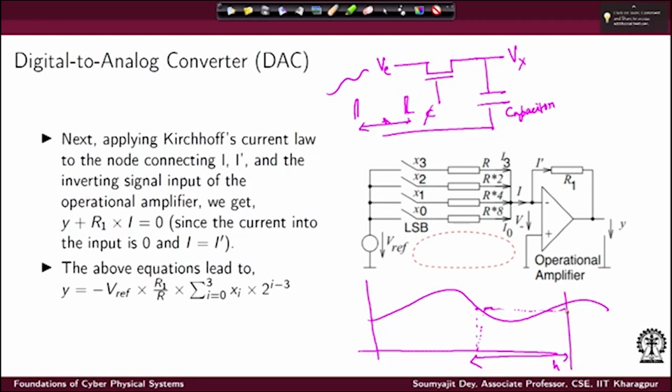So from this point it will again start and get the charge again, and then again it will try to hold the charge. So in this way it's basically sampling in a small amount of time. Depending on its capacitance value, it will get the charge and hold the charge with very small decay up till the next point, and from the next point again, depending on the voltage there, it will again lose or get further charge, right? So that's how a sample and hold circuit will work.